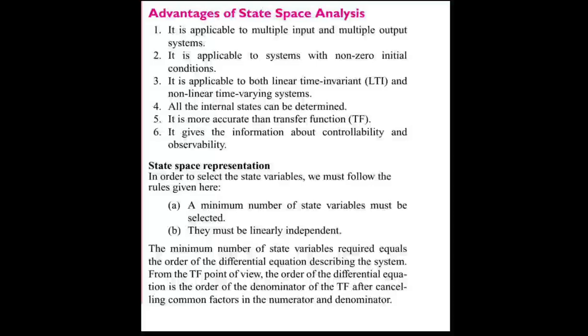State space representation. In order to select the state variables, we must follow the rules given here. A, a minimum number of state variables must be selected. B, they must be linearly independent. The minimum number of state variables required equals the order of the differential equation.